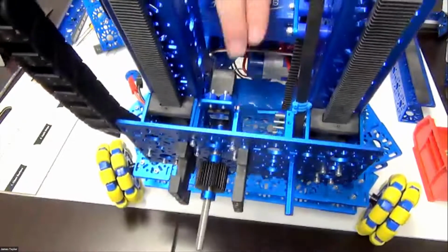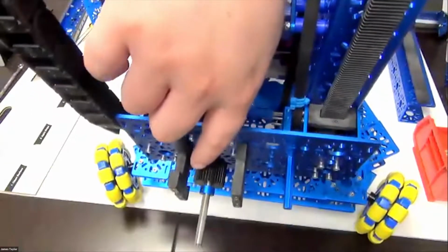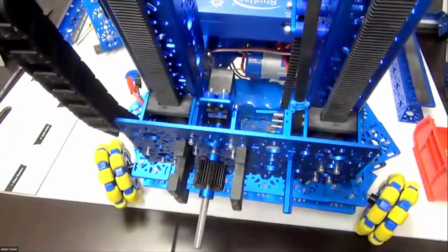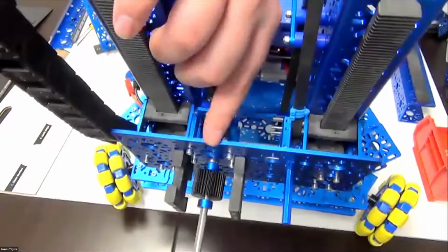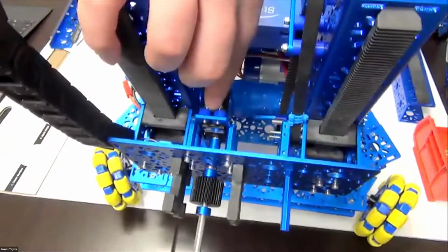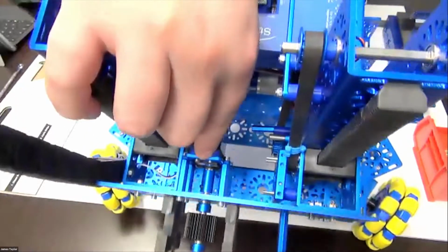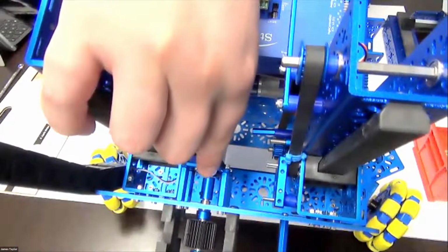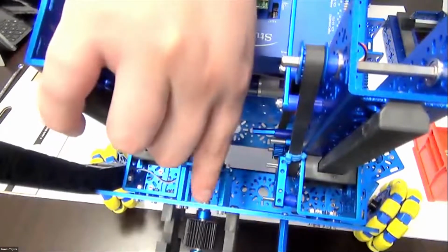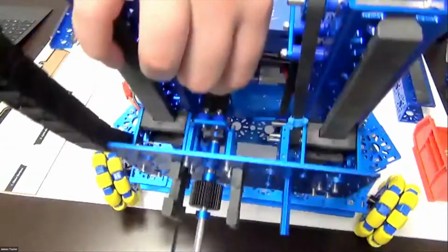Okay. Here we have the servo motor, which will drive the pinion gear for the differential. I put some 5mm standoffs here to push the servo away from the plate. This allows, if you can see down there, for the shaft adapter to be pulled away from the front plate and allow for a bushing to be put in.